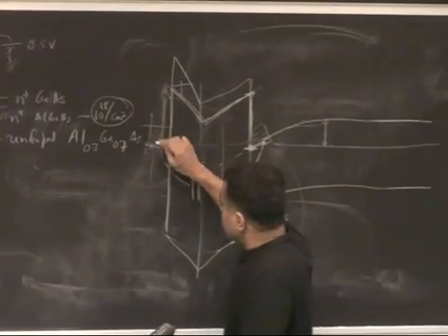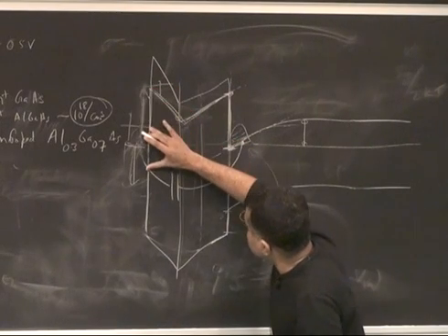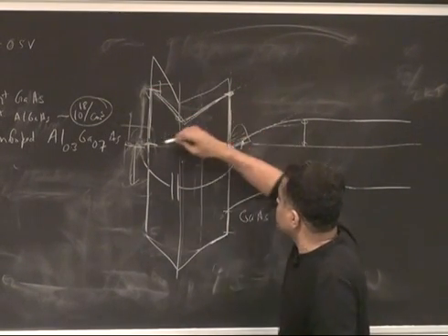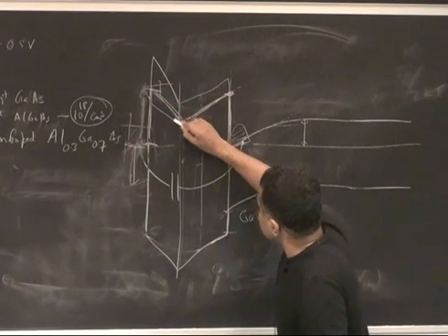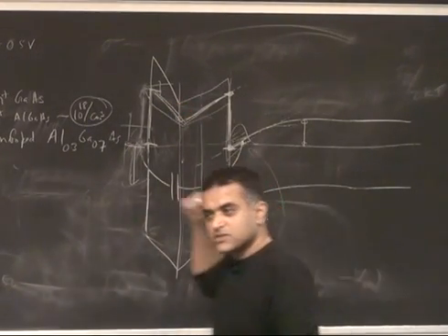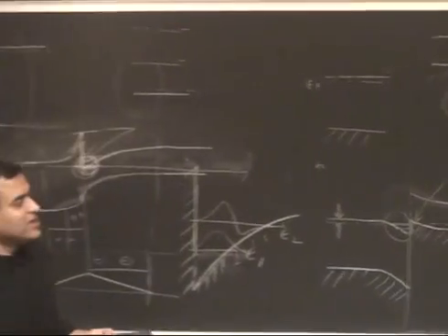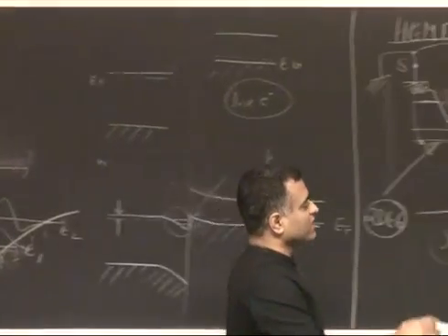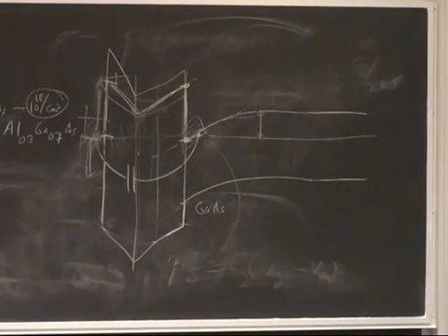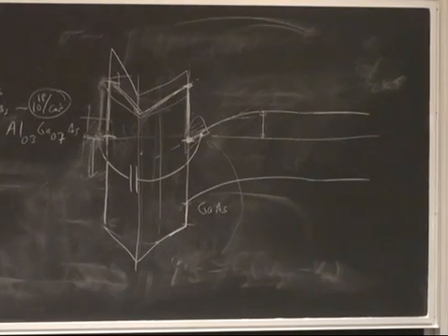And on, if you apply positive voltage, as you can see, you pull the whole thing down, because band offsets and Schottky barrier heights do not change with voltage. So when you pull it down, this will go like that, and the quantum well will get deeper, and you get more electrons here. Does it make sense? You can completely calculate that self-consistently, solving Poisson and Schrodinger, but you can do a lot just by writing analytical equations, and they take you pretty close to the correct answer without going through all the details of the problem here.